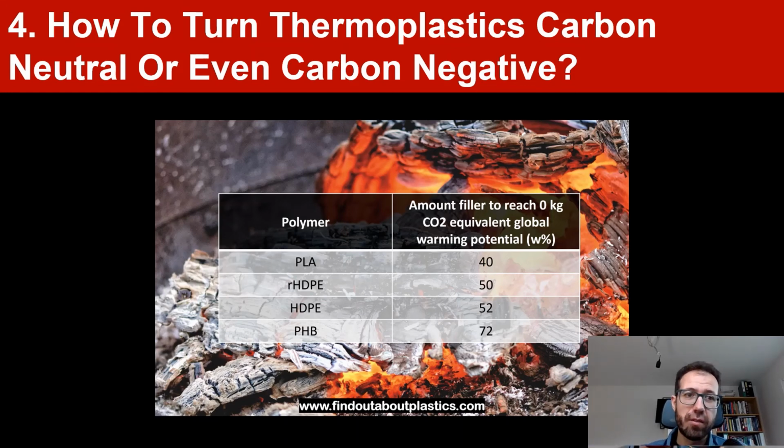What else they found out? They found out that biochar increases the tensile strength of recycled HDPE by 45% and also stiffness by 126%. So it's also a good mechanical reinforcement filler. And also the flexural storage modulus could be improved by 79%.